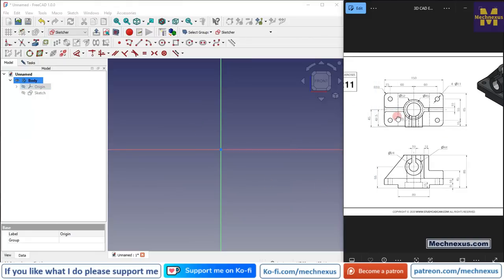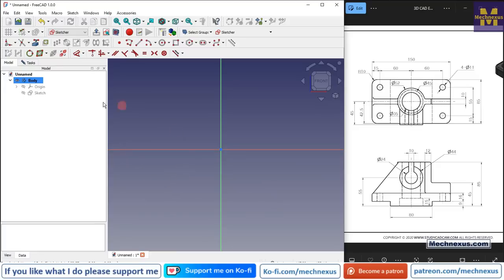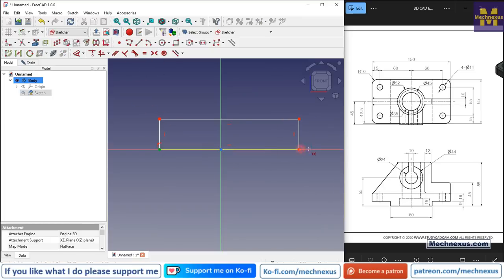And now we will first create this profile. So first we will select the rectangle tool and create a rectangle, and now I will make this rectangle symmetric. Select this point and the axis, and now we will give the dimensions.